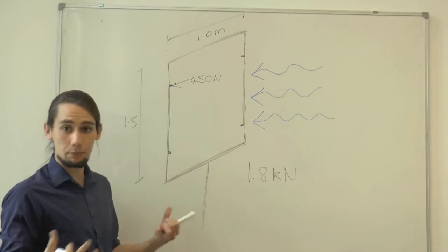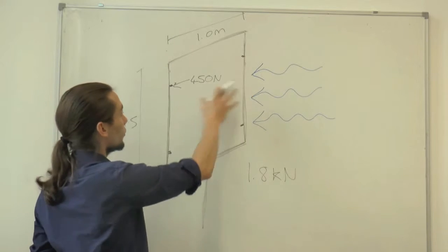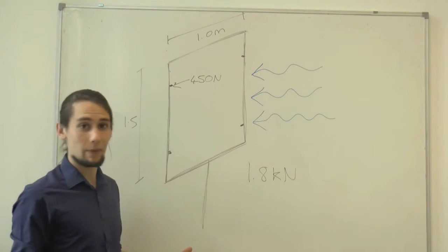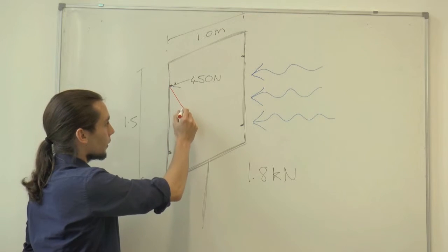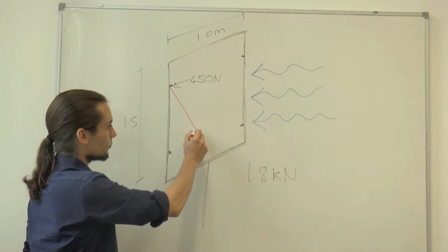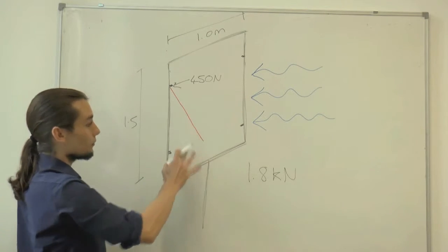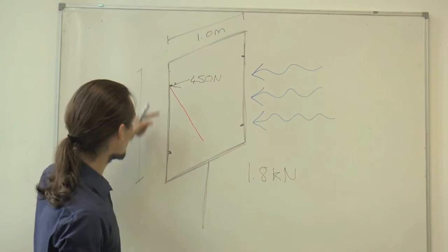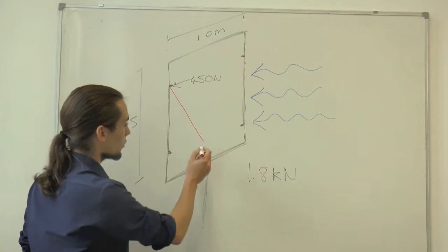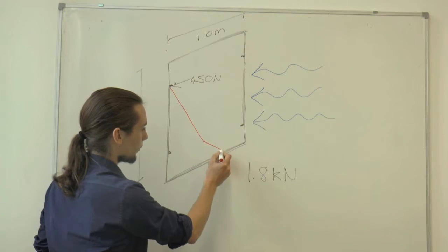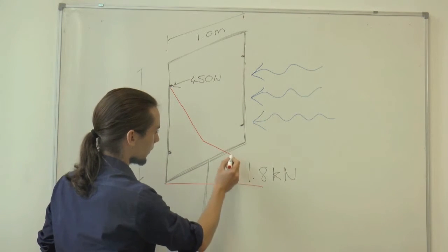And it's basically acting like a cantilever, because it's not really restrained at the top. These 2 members are basically acting independently. So as we move away, we get a familiar triangular distribution down to this second one, where it's going to increase because we're going to have the effect of both of these 450 newton loads. So it's going to kink out again, and the bending moment diagram is going to look,